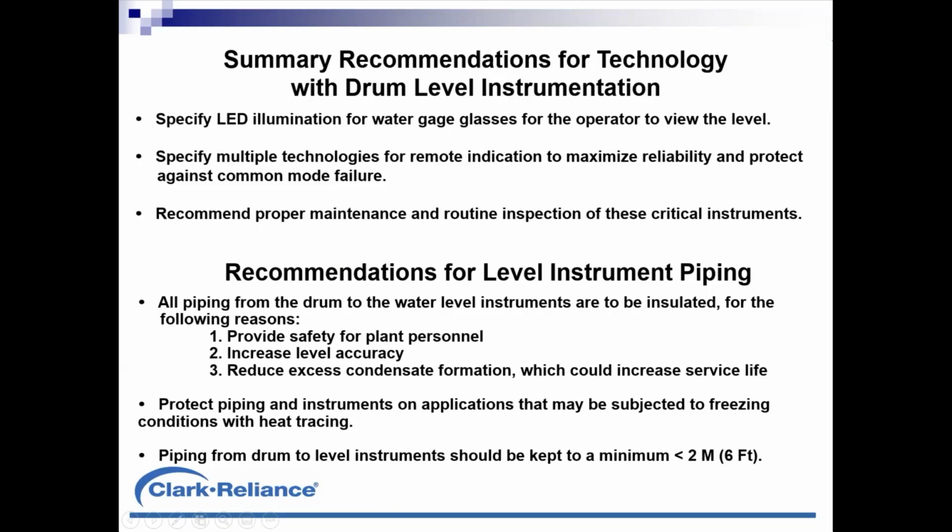On your piping, always do that insulation. It takes care of personnel safety. It helps increase level accuracy against temperature loss, and also reduces condensate formation in high temperature steam service applications, which could help extend service life of the instrument and improve level accuracy.